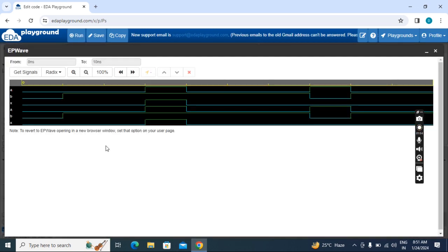Now here we got the transcript and now we can get the wave also. Here you can see. So when I click on the wave, somewhere here, what is it showing? So this is A0, B1. What should be the output value? 0. Like that you can click anywhere and you can check the waveform. Here you can use the right button, left button to zoom plus minus. You can change the radixes. Okay. You can do these things also.